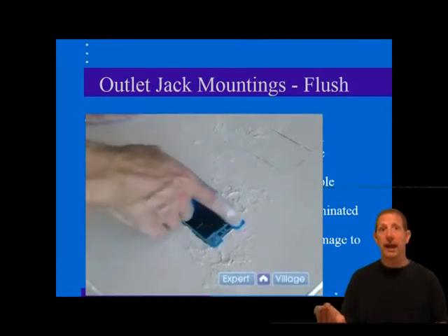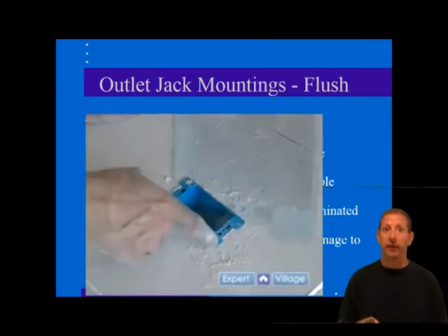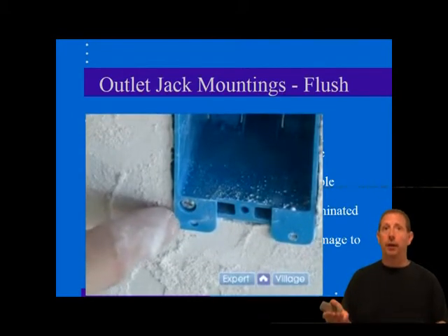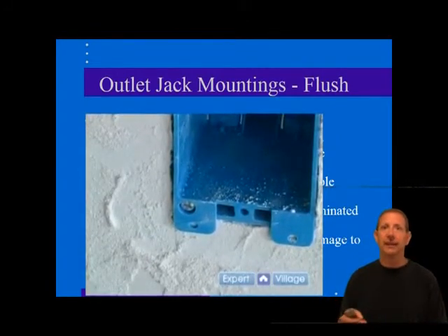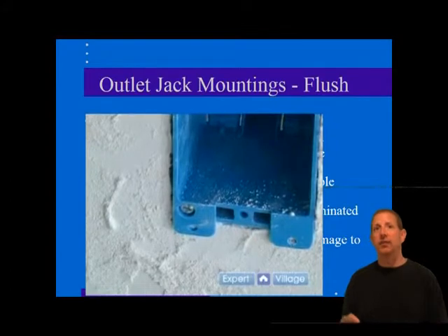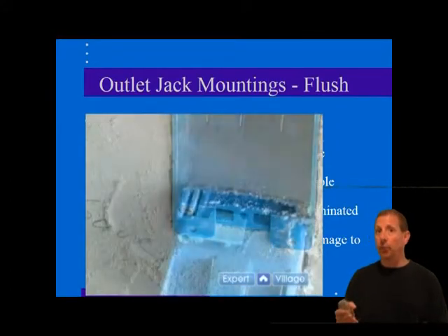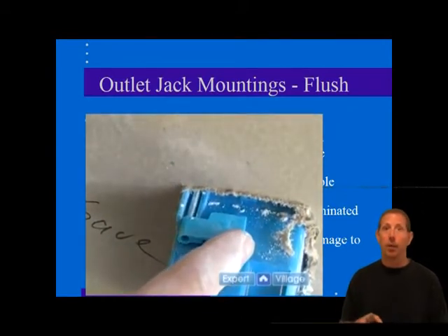the ring. An alternative design has a vertical screw slot incorporated into the metal fingers. After the fingers are bent into the mounting hole, a provided screw clamps the front flange of the ring tightly into the wall using the slotted finger as a rear clamp. This prevents any undesired movement in the ring that would occur with the other type of rings.